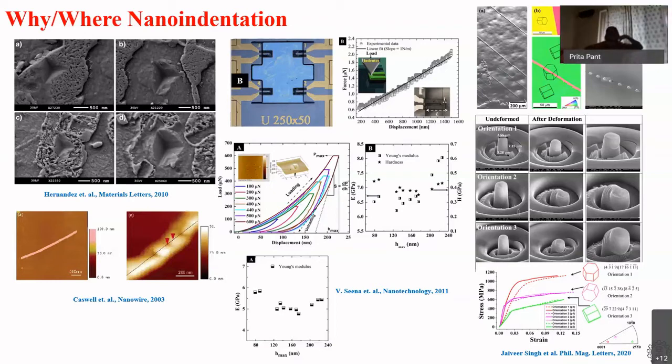it in a sample of water, or put a few drops of water on it. If it has the pollutants that I'm trying to detect, the cantilever will bind with those pollutants and it's going to bend. And I can calibrate the bending of this cantilever to figure out how much pollutant there is in the water sample that I've just put on the cantilever. Okay. Now, all of this bending is a function of the stiffness of the cantilever. So you need to know what the stiffness of the cantilever is.